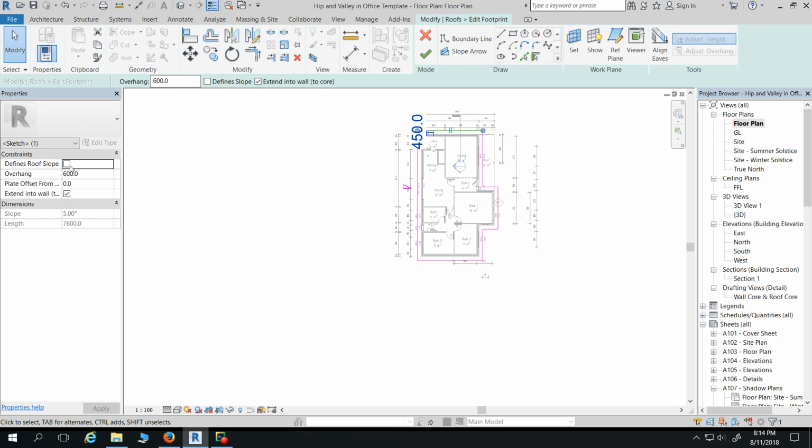So, do you want to change this one to a skinny? So just let go back into the sketch. Edit footprint, sorry. So just check that edge, yeah, and go edit footprint. And jump back to your footprint. It's probably the easiest way to do it.